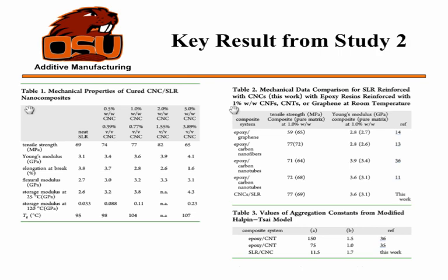So they were able to retain the polymer properties and at the same time get some enhanced strength and mechanical properties. These were some of the numbers which they got for tensile strength, Young's modulus, and elongation for different percentages of CNCs which they added. The table on the right shows a comparison with other reinforcements like graphene nanofiber, carbon nanofibers, and carbon nanotubes, and it's seen that cellulose nanocrystals give much greater enhancement in mechanical properties compared to the other reinforcements.